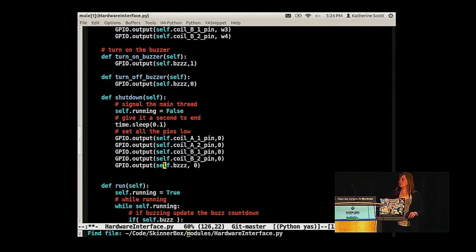This is just a good point for building stuff. If you're using, say, a Raspberry Pi or some other interface to build hardware, one of the greatest things you can do is run the IPython Notebook and bring all your GPIO pins in, because then you can interactively bring them up and down really easily. If you have a circuit board or a breadboard and you're trying to debug what's going on, you can bring them up and down, put your multimeter on there and say, oh, yes, it came up. Okay, so it's working.